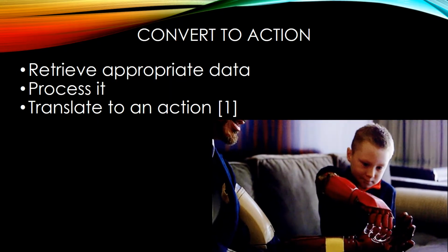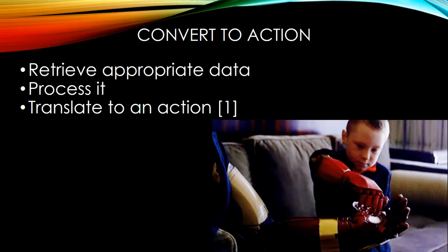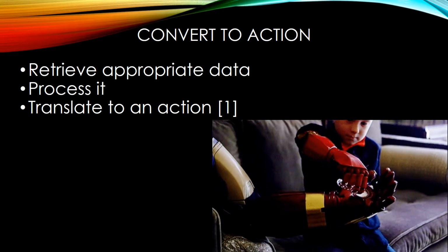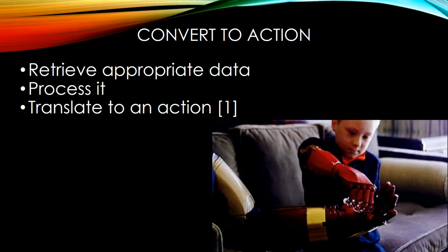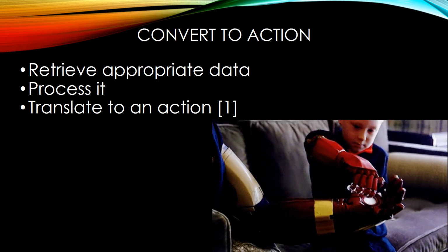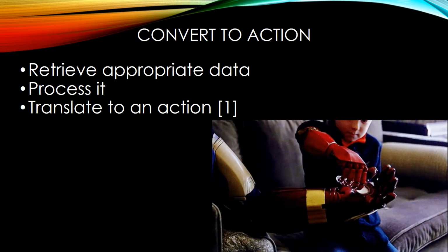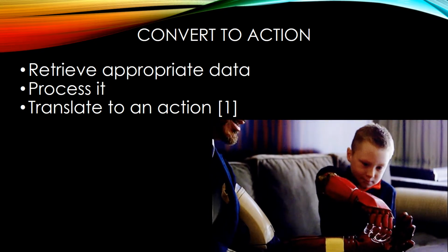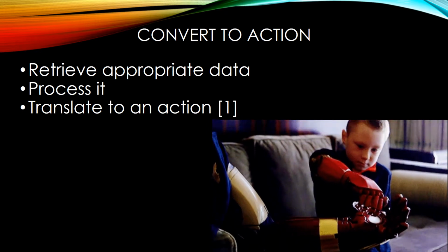Once the proper features have been identified, we can then get the appropriate data from the interaction of the neurons. The signals that we get will be very small and susceptible to interference, so they may need to be run through a filter and an amplifier. Once we have that final output from the neuron, we must translate that into an action.